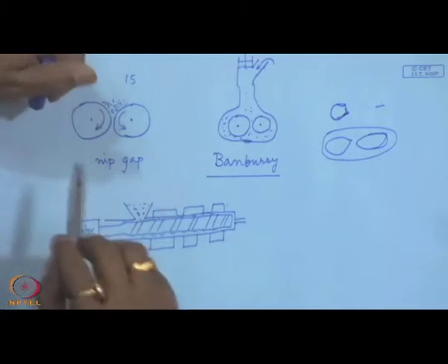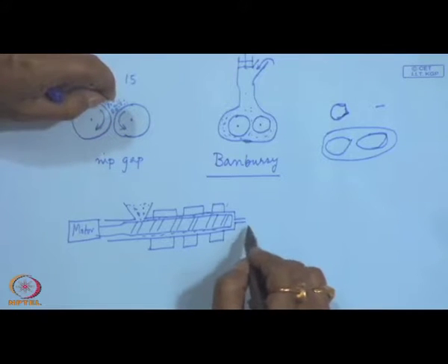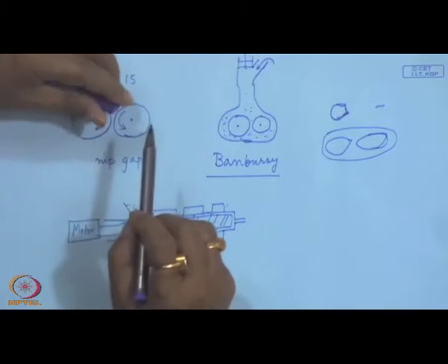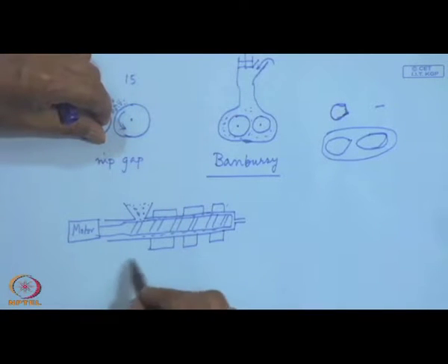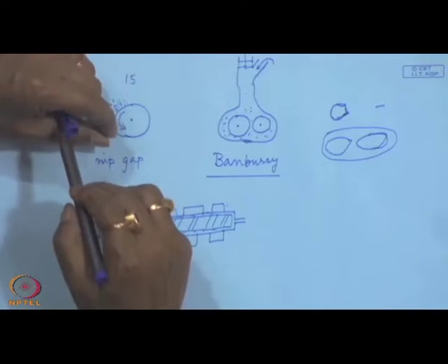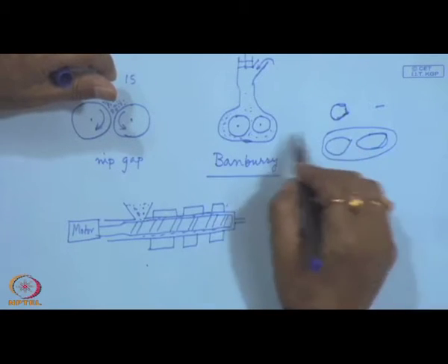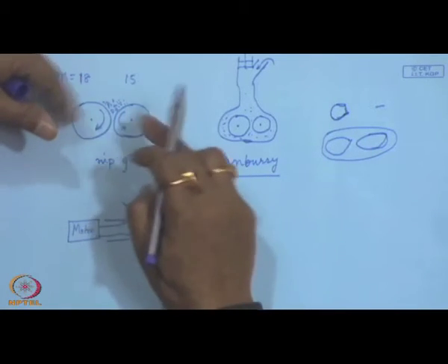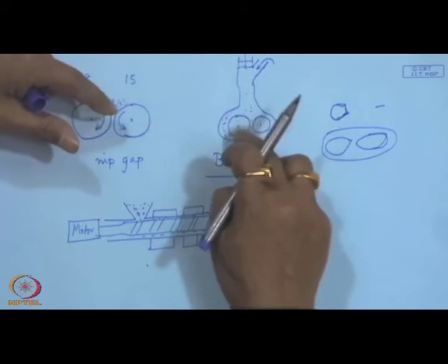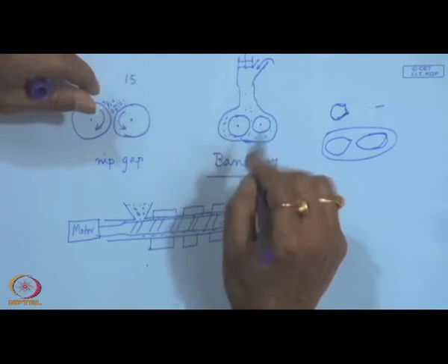This is also a technique for manufacturing say pipes, tubes or coating of wires, etc. It is also used for blending of the component polymers. This extruder can be a single screw extruder or there can be a twin screw extruder within the same barrel. The twin screw extruder is a kind of modification of the open two roll mill, and again a modification of the internal mixer in a continuous way.